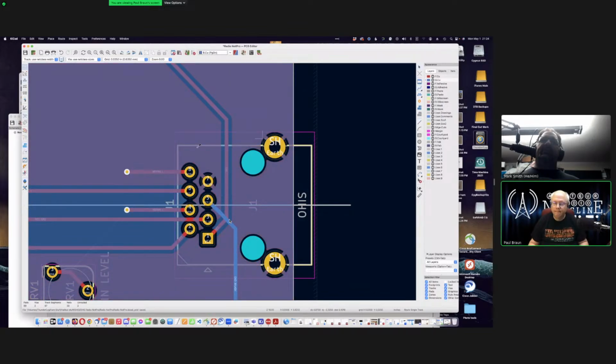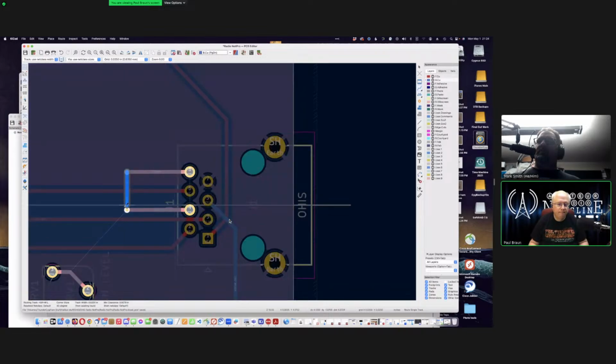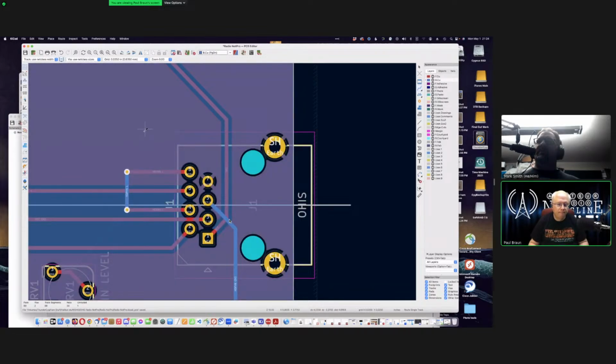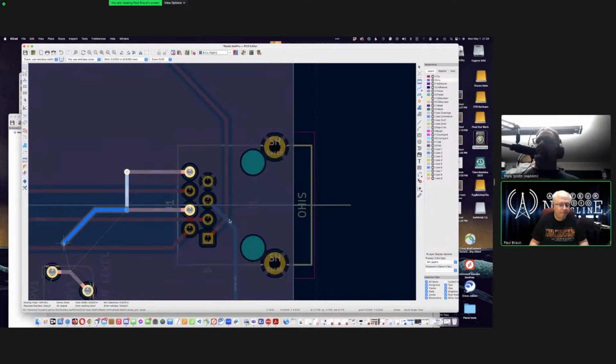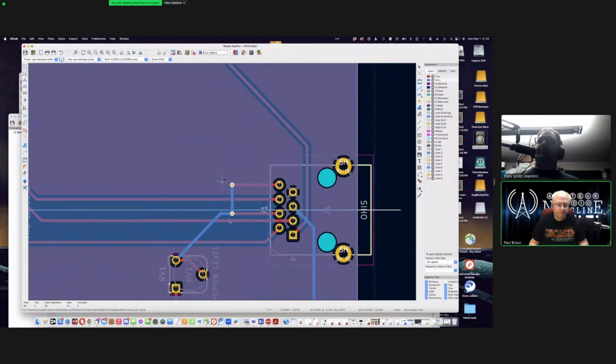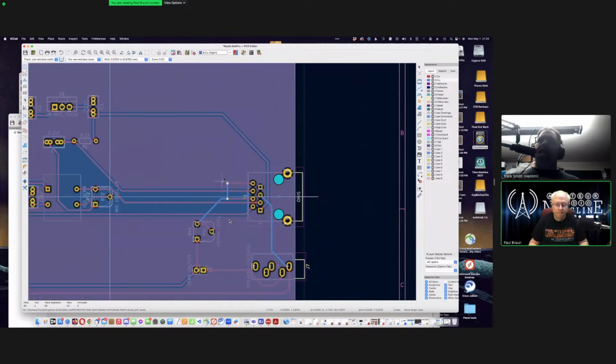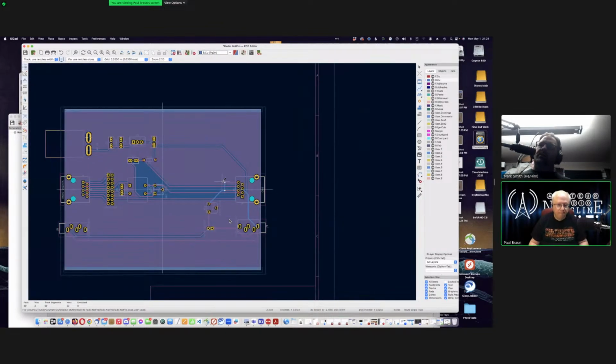Nope, trace, not a line. There you go. Click to there, and then from there down to the pot. Either trace, it doesn't matter. Now I think you're done. Hit B. Let's see what islands we've created.